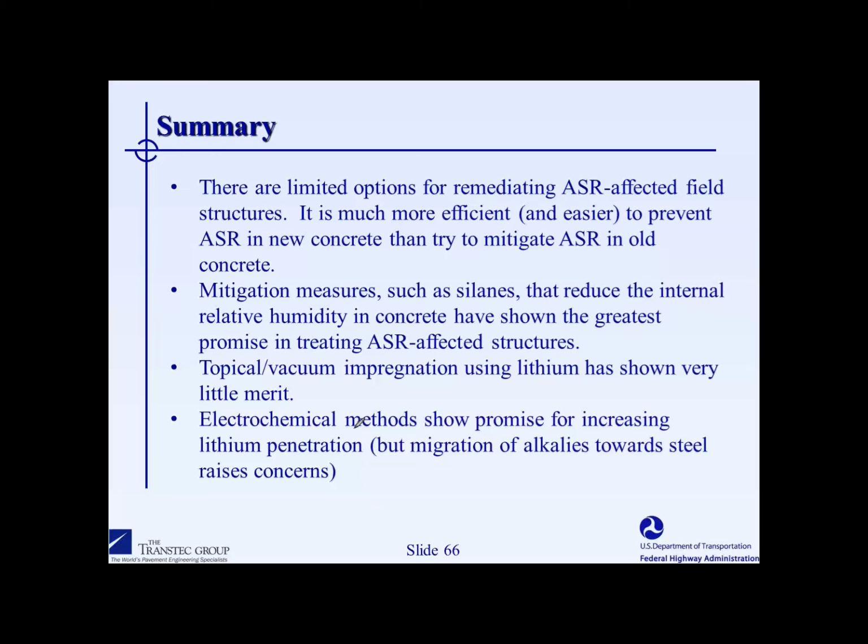The first one, has any research been conducted using integral waterproofing agents or water-repelling admixtures to improve resistance to ASR for non-reactive aggregates? We've done a little bit of work, but it's too early to really determine what the effects are. Most of the work that our group has done as a whole has been more on existing structures and applying some kind of a hydrophobic coating such as silanes. We have done some work where we've mixed integral water repellents into the concrete, but the jury is out right now as to the efficacy of such treatments.